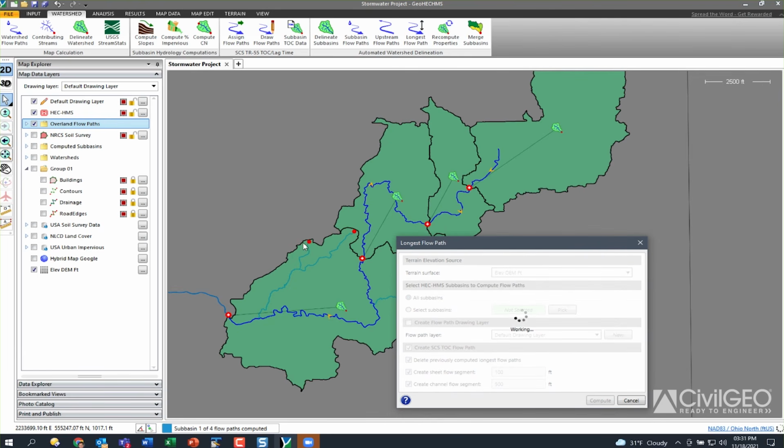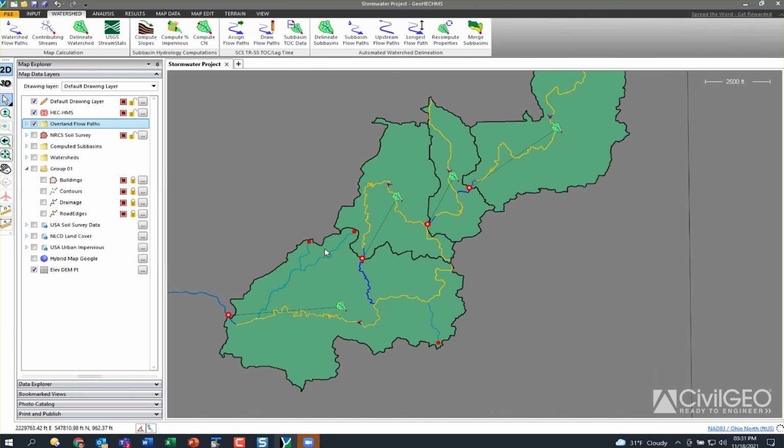Every 10 meters, every 30 feet, it's putting a water drop down and tracing out where it's going to go. Again, it's running on your graphics card. We can spin that up pretty fast because your graphics card actually has multiple processors on it. It's been optimized to play video games, right? So we're using the same architecture here to calculate all this stuff. It ends up with hundreds and hundreds of different flow paths and then figures out which one's the longest. And then when it's done, it's going to extract a profile view of that.